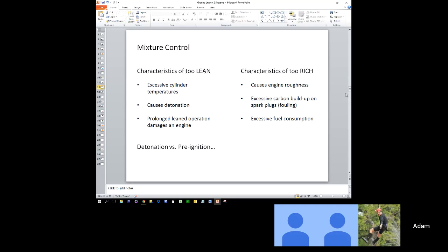So essentially, your fuel air mixture was appropriate for the altitude you're flying at, and as you came down to airport elevation, now the air gets more dense and you don't have enough fuel in your mixture to compensate for the increased amount of air going to your engine. So your engine's running too lean.